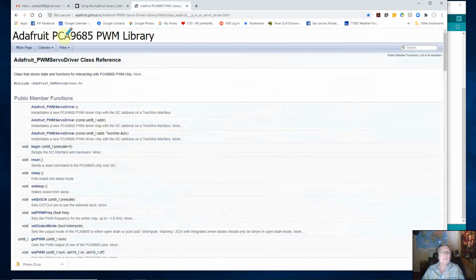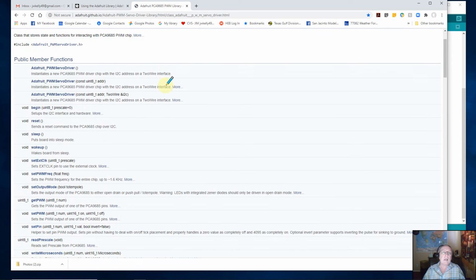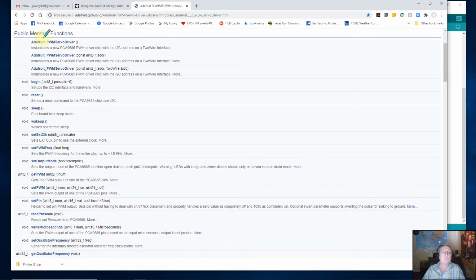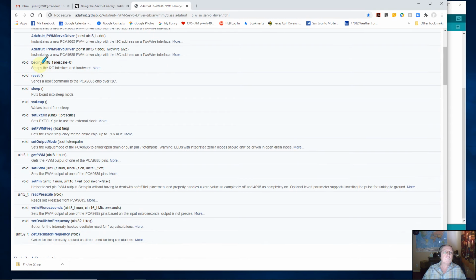Here I went to the PCA 9685 pulse width module PWM library. It gives you a high-level overview of all the different functions that the programmer wrote that you can use. You don't have to write any of this code. Like I said, you just have to know how to use it. So you can peruse this list and say, I'm trying to do this.